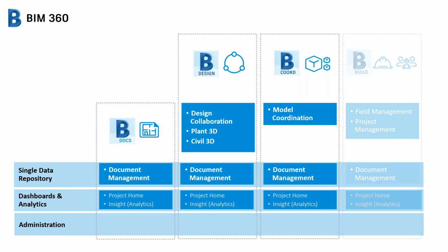The models can be copied into a collaboration space automatically using BIM 360 workflows as well. And Navisworks 2021 also includes integration with the BIM 360 coordination space, which includes the ability to view and edit issues. So let's look at some of these workflows in the next couple of slides. Like I said, this gets a little bit deep here, so if you've got any questions, please ask.